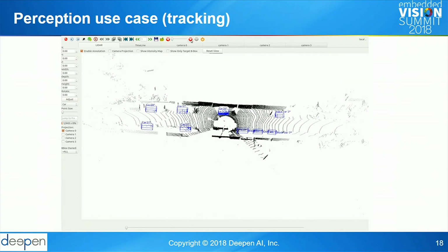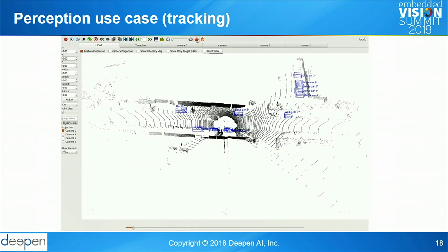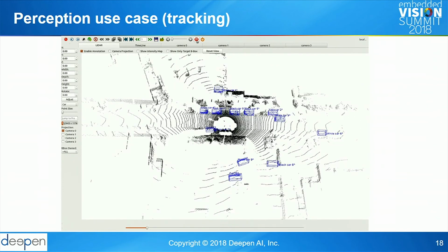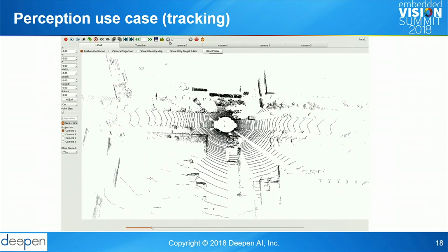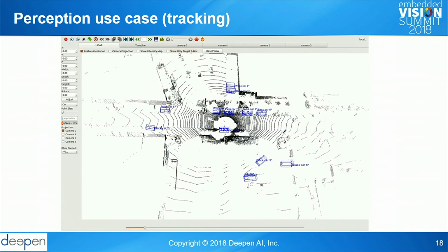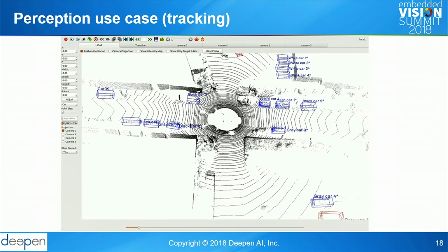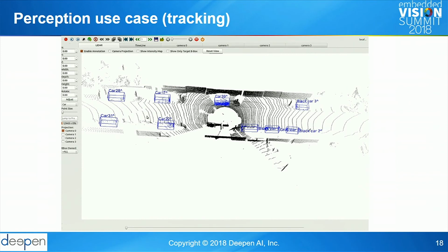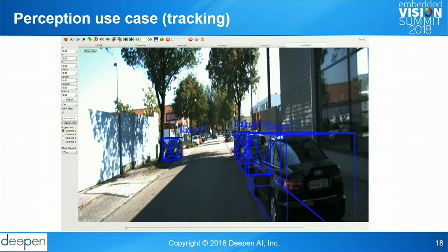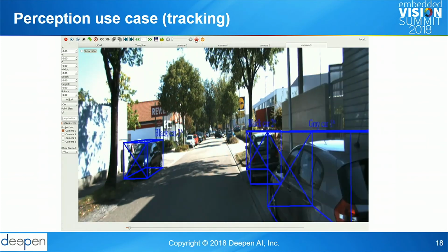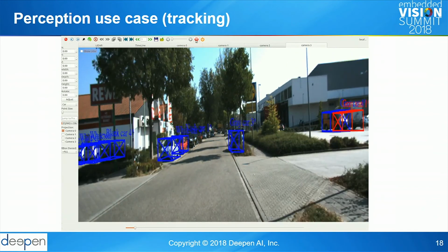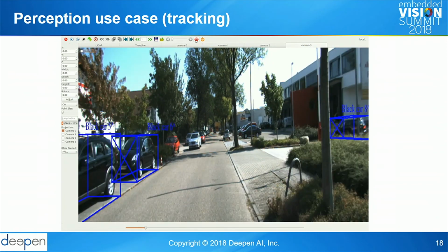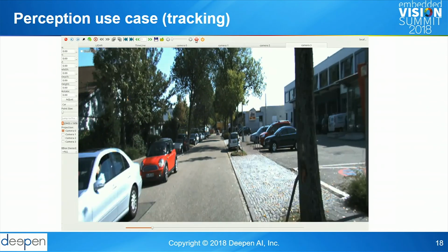This is a video, in our tool, to give an example of the tracking and the classification. Cars are popping up based on the range accuracy or the range certainty. Most LiDARs today, the highest range we've seen is around 250 meters. But at 250, you're getting very little number of reflections. With some vendors' best, highest end LiDAR, in order to see something at 300 meters, to get 1 photon back, you need to send about 30,000 photons. So it's a very low ratio of what you get back at longer distances. And this is just showing you how the LiDAR annotations are reflected into camera, and that can help with, like I said, prediction, classification, and tracking.